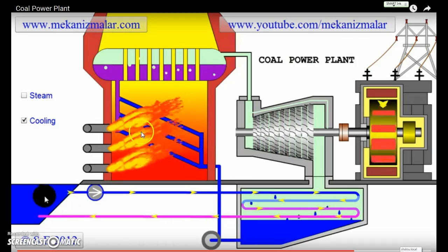There's one final note. This pipe system here is called a heat exchanger. Why? We're exchanging heat from one thing to another. So what's heat being exchanged between? The energy starts out with the combustion fumes from the coal, and those combustion fumes exchange their heat through the pipes, through the heat exchanger, to the water. This is a heat exchanger too, down in the condenser, but we don't typically refer to it like that. Instead, when we talk about a heat exchanger in these IB problems, we're referring to this one inside of the boiler, or as part of the boiler system.